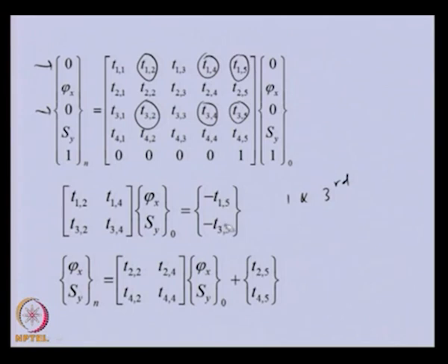This is the external force components. So, basically I have taken out the first and third row and I have recombined them. Similarly, if I take out the second and fourth row, I will get this equation. This is from the second and fourth row. So, here also the unbalanced terms are coming.